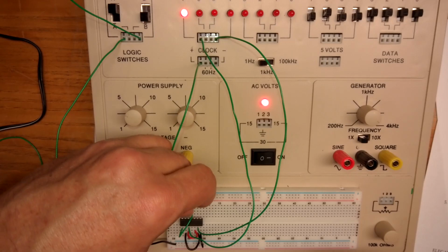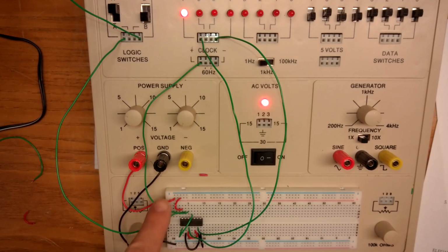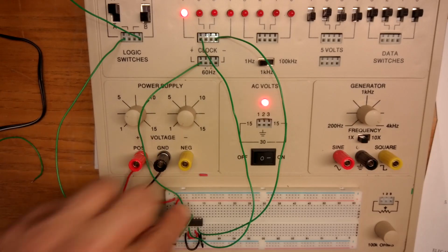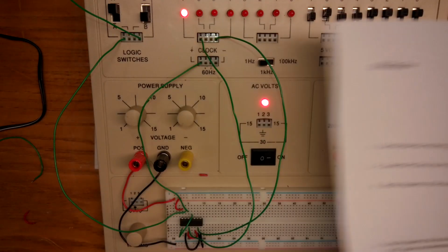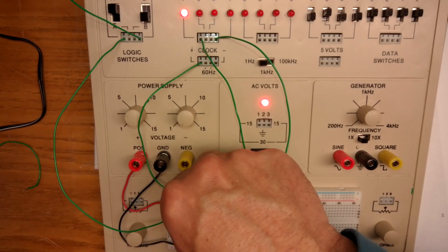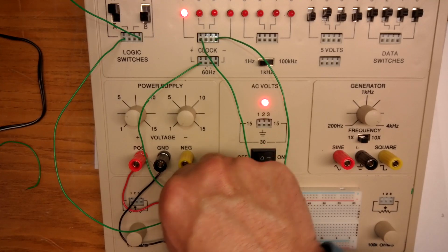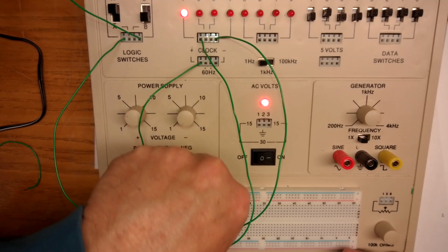And right now I've hooked this up. So you can see I have clock in, S in, just like we said, and the output runs into this NAND gate. Okay, now the other side, we need clock in. So I'm going to take the clock down here. I don't need two going all the way up to the clock. I'll just take the clock right here and hop it over.